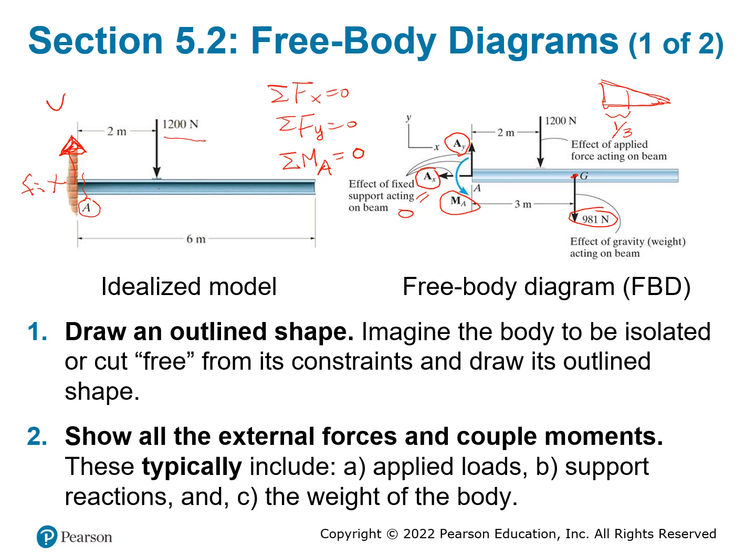The reason is when you select point A, these two forces, Ax and Ay, will not contribute to any external moment, because these forces are applied at the same point. So they are not going to have any moment. You only have the reaction moment, the moment A, that exists at that point.